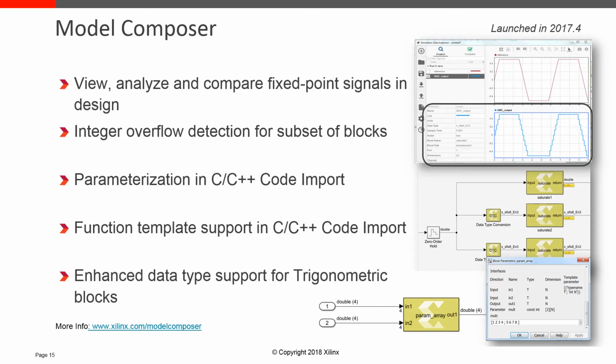For Model Composer tool, which was launched in 2017.4, users can now view, analyze, and compare fixed point signals in the design. Integer overflow detection capability has been added for several blocks in the design using Simulink's data validity diagnostics. This detection enables debugging issues with integer overflows and choosing optimal data types.